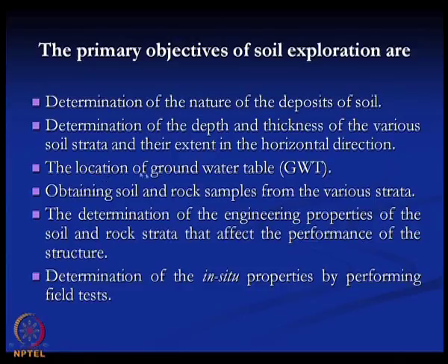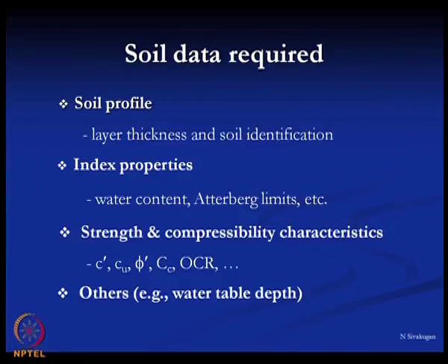Then the location of the groundwater table, because the groundwater table also plays a very important role; obtaining soil and rock samples from various strata; the determination of the engineering properties of the soil and rock strata that affect the performance of the structure; and determination of the in situ properties by performing field tests. So, these are the objectives of soil exploration.